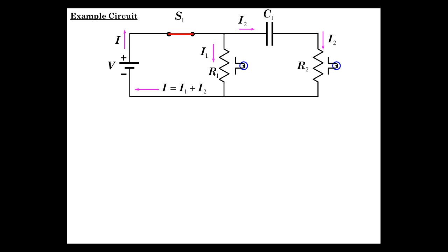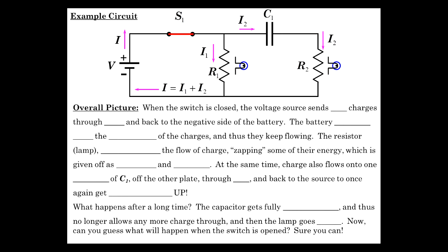The problem is, you might think over here, I've got to decide what to do at the capacitor, and once I'm done with that, I'll decide what to do here. Well, no. Any charge going this way is then also moving everywhere else in this loop. So just keep that in mind.